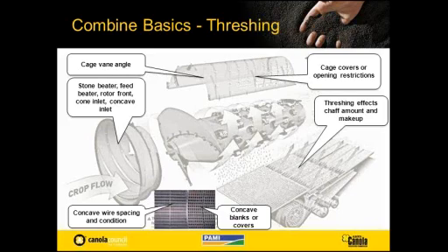In the concave area, the wire spacing makes a difference. Again, as I said, I was talking about the snap part of heads or broken up straw. The narrow wire tends to keep more large particles up on top. They usually don't have as much open area, so you get into concave with wide wires, they have more open area.